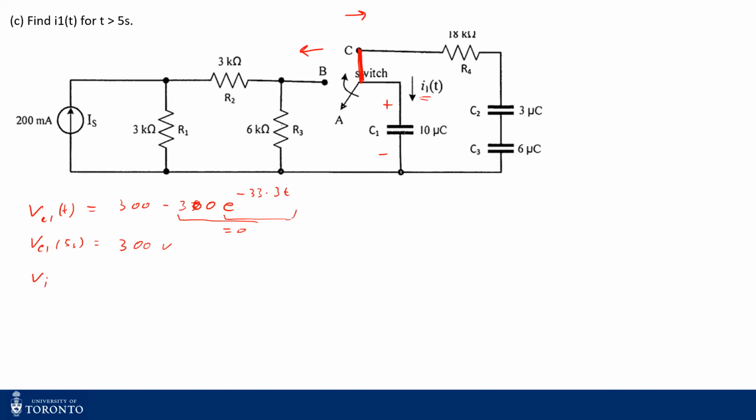In this case, when the switch moves to position C, so that's your initial, right? And what's your V final voltage? So if you keep it connected, you know that your capacitor will discharge through this resistance to 0 volts. So your V final is just 0 volts, right?